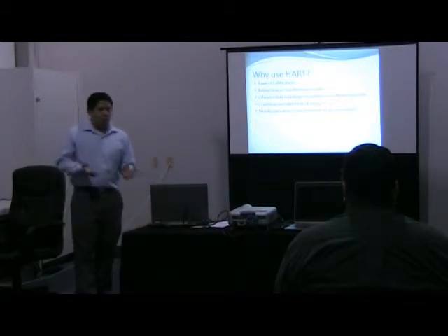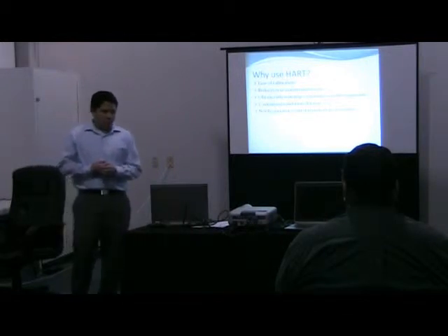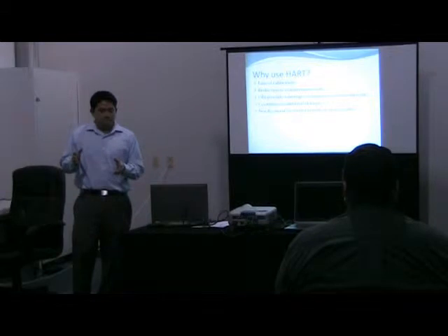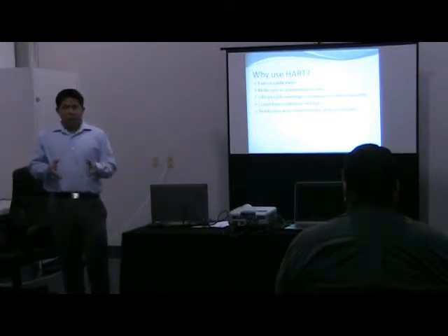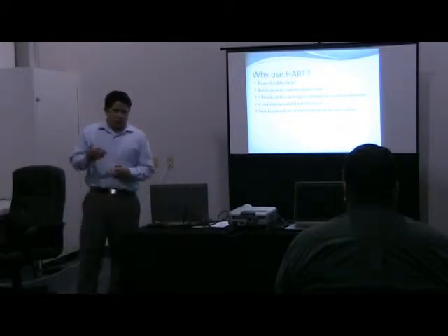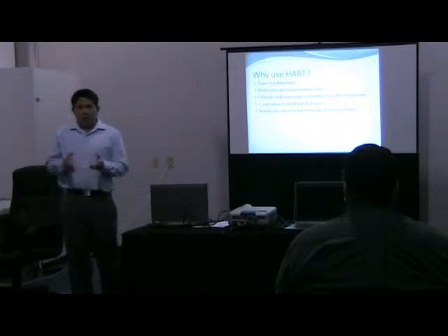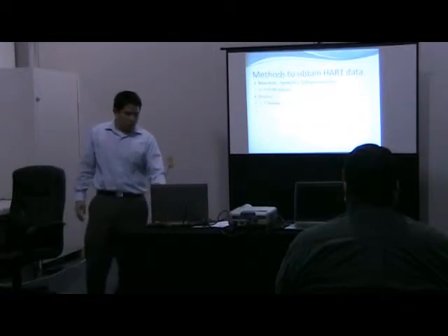So I use HART, as we all know, it makes calibration easier. It's known for its reduction in maintenance costs. It's used to give early warnings to staff on variances in not only the device but also the process itself. It's used to continuously validate your loops, and it can notify the operator or the control system of a device failure.